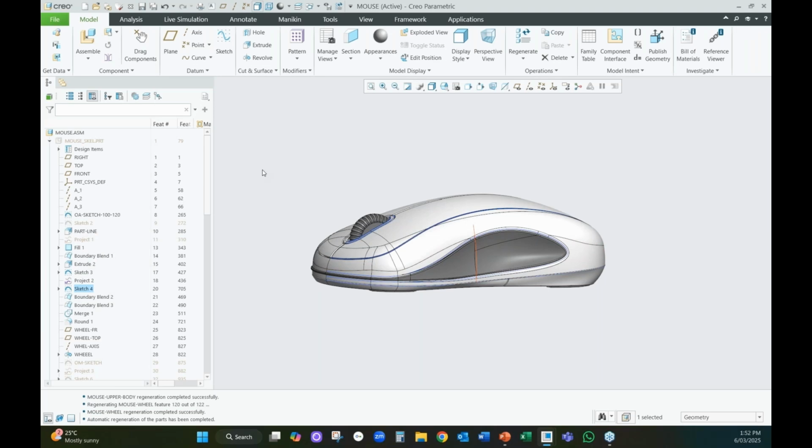For multi-body modeling, which I'm using now with a current client, using all solid multi-bodies, the real beneficial trick I've found is this: say you've got three parts, A, B, and C. I will often share all three parts into, say, the part file for part B, just so I've got that awareness of where parts A and C are residing in space.